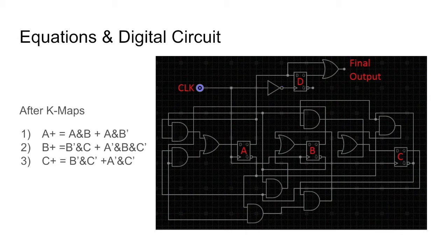In that circuit, adding a NOT gate on the clock will help get a differential clock and a clock bar, and the extra flip-flop D will trigger on the clock bar rising edge to shift the output A by 90 degrees. In addition, an additional gate will OR two outputs of flip-flop A and D to produce a 50% duty cycle output. We build a 50% duty cycle circuit in a different block so that it can be reused in any odd integer clock division.